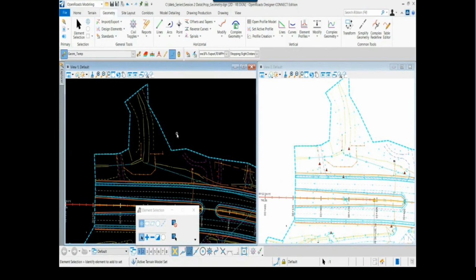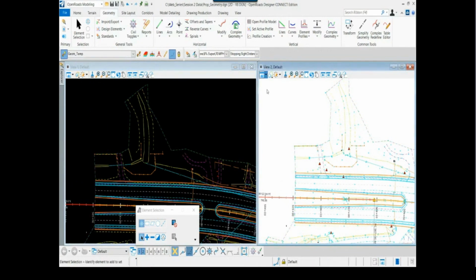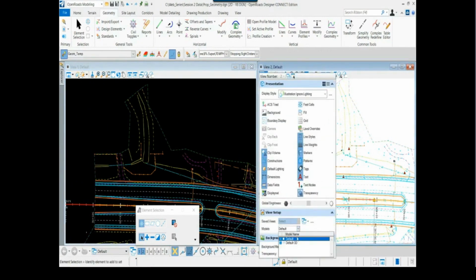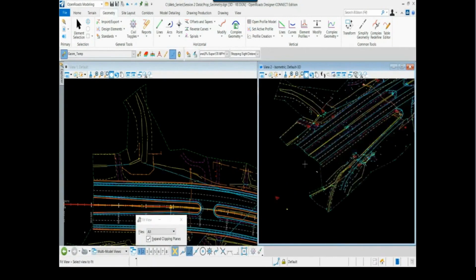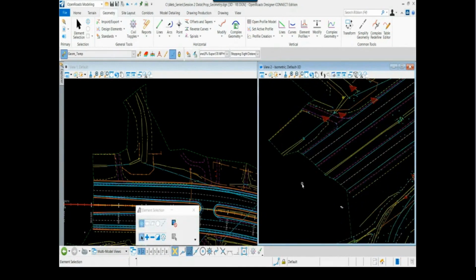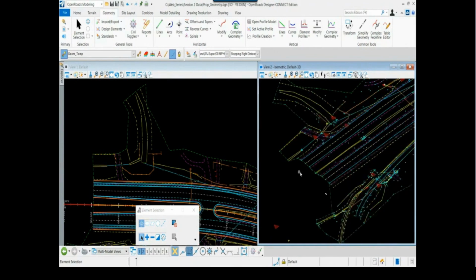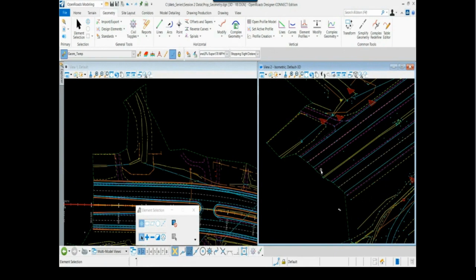Not only does it set the terrain model active, but by activating any design element that has 3D in it, meaning some sort of elevation definition, OpenRoads Designer also moves all of the project data into a three-dimensional model. So now the data that I referenced to my original 2D file has been placed in a 3D model as well. The elevations from my topo, the elevations from my resulting terrain model, all that data is in a 3D model in my DGN and available for me to use.